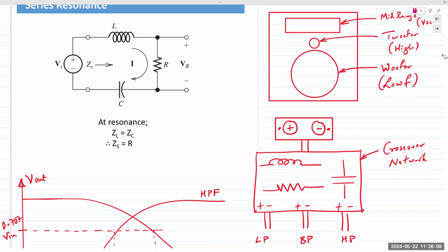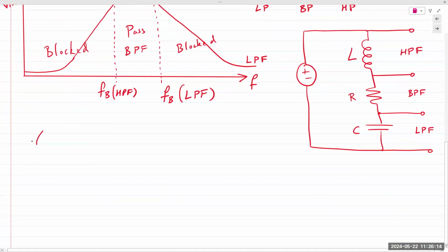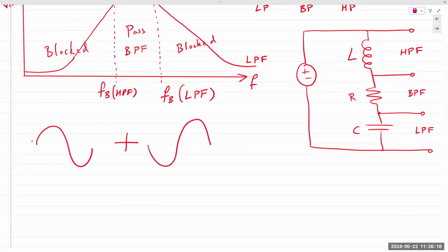Remember at the beginning of chapter 1, I showed you something like this. If you have a signal and you add it to the exact same signal, but 180 degrees out of phase, what do you get? 0. Real life application? Anyone remember? Noise cancellation. You take an incoming signal, invert the phase by 180, add it to the same original signal, output goes to 0.